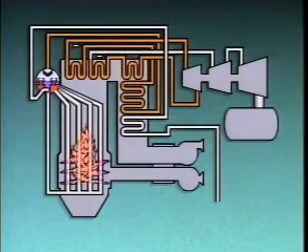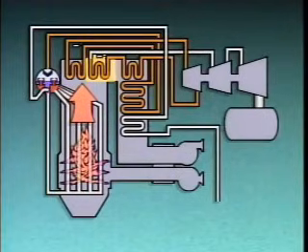After the steam flows through the primary reheater, it moves on to a secondary reheater. An attemperator, located at the beginning of the secondary reheater, is used to control the final temperature of the superheated steam leaving the secondary reheater. The attemperator sprays water into the steam flow if the steam gets too hot. The secondary reheater in this example can also be classified as a radiant reheater because it's located in a line of sight with the boiler flames and receives most of its heat by radiation from the flames.